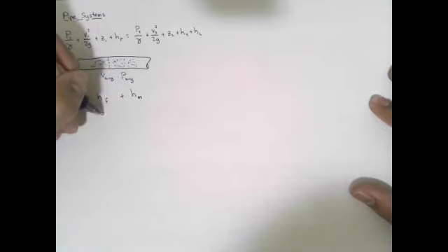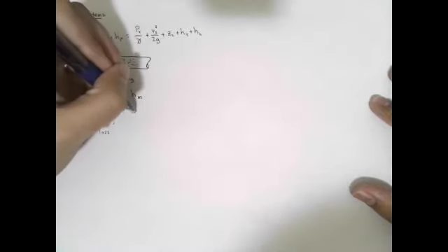So we have a friction term that we call friction loss, or sometimes we call it major loss. And we have a component term. And when I say component, essentially, I mean everything else, everything that's not friction. So a component term is called the component loss, or sometimes called the minor loss. The reason we call the friction loss the major loss and everything else the minor loss is because the friction loss is pretty large compared to the loss from an individual component.